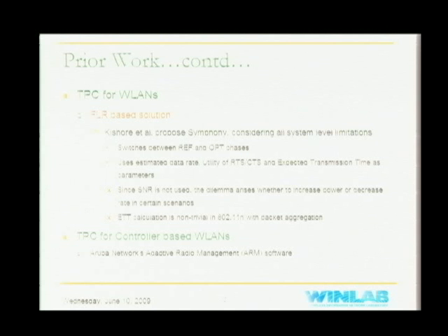What is the problem with node mobility? I didn't quite catch that. For example, if the frame loss rate increases in a non-SNR based solution, you will see packet losses. But the source of frame losses cannot be identified as whether they are due to interference or node mobility. But if you have SNR or RSSI feedback, then you can make the distinction that there has been a change in the link condition between the transmitter and receiver, or there is some source of interference in the medium.